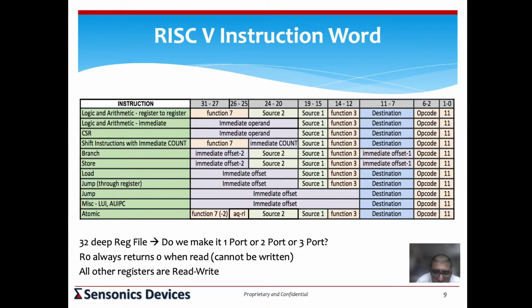So the pseudo instructions that you're not using can be used, the no-ops that can be used for hints to the hardware. There's a whole class of hints, which means that you have a no-op. For all practical purposes, it's a no-op. If the hardware didn't implement it, it would walk through the execution as a no-op. If the hardware knew what you were trying to talk about, that hint would let the hardware trigger into some other areas, and some dedicated hardware will work on that.